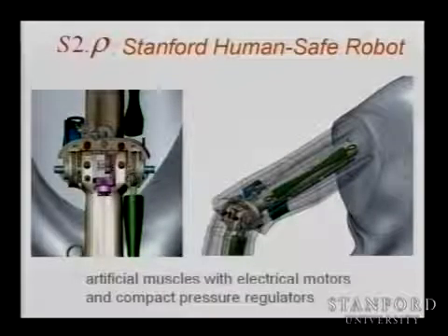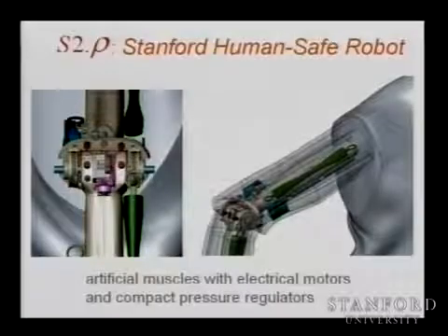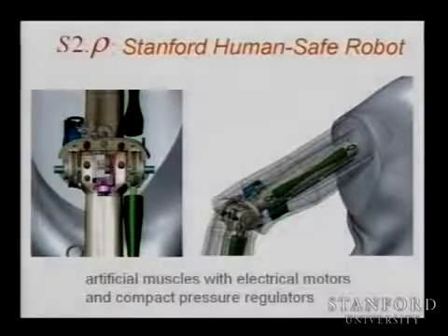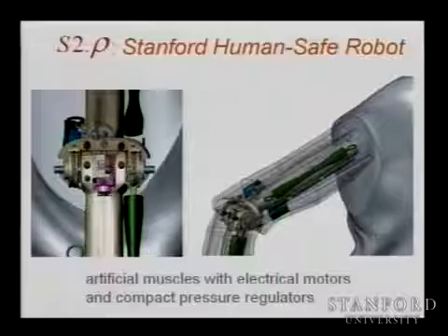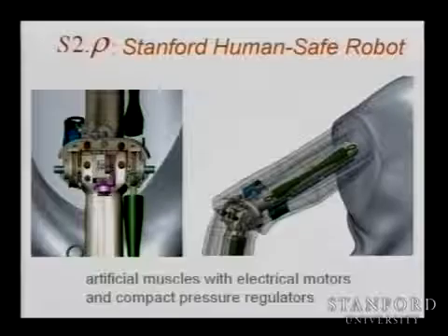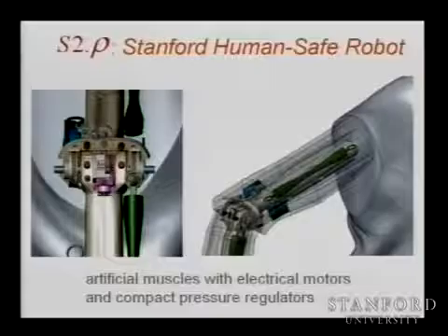So we started building a robot like this, and the idea in this robot is that you use bones, muscles, and air pressure, so you are bringing the energy through the air, and now you can lift the robot, you can produce the large magnitude of torques needed, and then you add a small motor on the joint, and this motor will allow you to get the dynamics. So combining the two, you get hybrid actuation that essentially leads to a safe robot design.